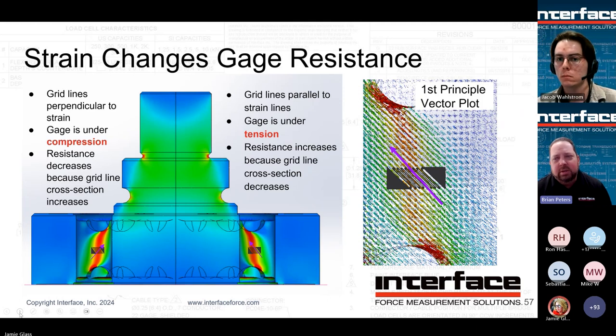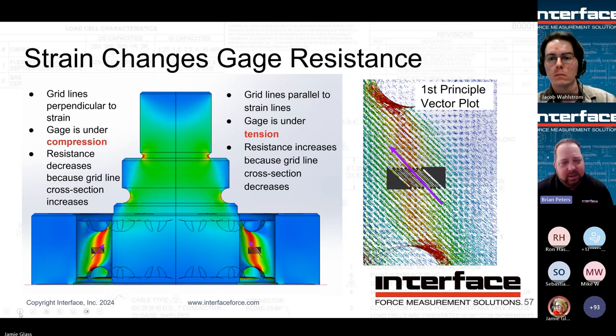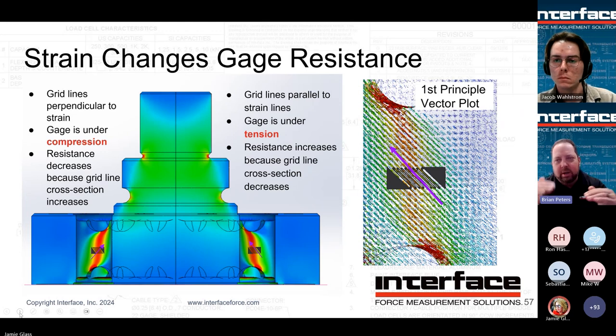If you look at our calibration grade sensors, for example, our 1600s, they have a pre-installed cal adapter. So that center stud that we see here in this picture would be threaded in, locked at the factory, and preloaded to ensure that as you operate within the capacity, you're not going to get any change in how those threads interact with the center hub, so you don't get sudden shifting of which threads are loaded, where the load goes through, which can then dictate a very slight, subtle change to the beams, right?